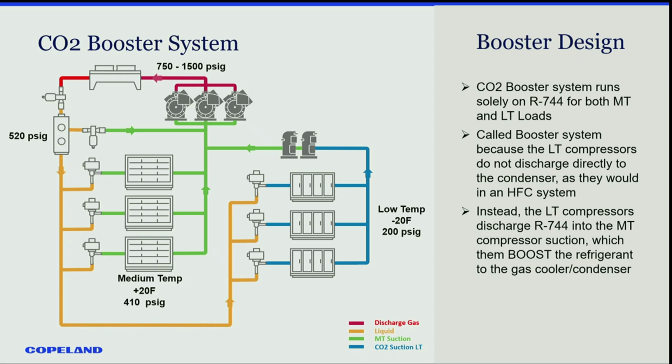I don't know if you've heard the term release events, but a release event is where you have a significant amount of refrigerant that blows off through a pressure relief valve. Not a leak on a joint, a pressure relief valve. That's a release event where now you've got to go look for refrigerant. They want to avoid that because sometimes if you can't get refrigerant for a day or two, you're losing everything in your store. So that's not a good thing, and that could be hundreds of thousands of dollars.